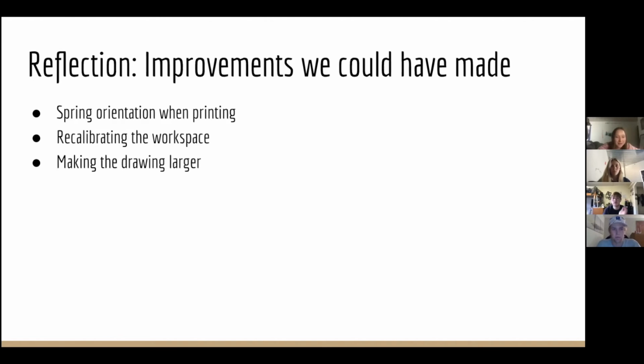In the lab, we had issues while trying to set the points for the circle. We later realized this was because the workspace was calibrated at an angle. To fix this problem, we recalibrated with precise jogging movements. However, if we would have recalibrated the workspace to begin with, we would have saved a lot of time.